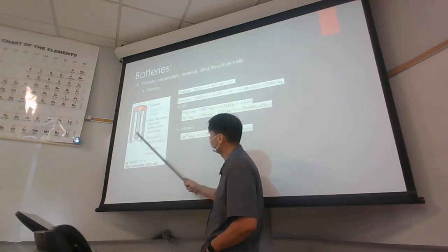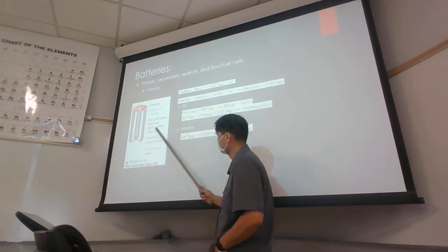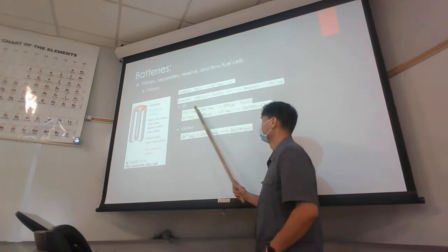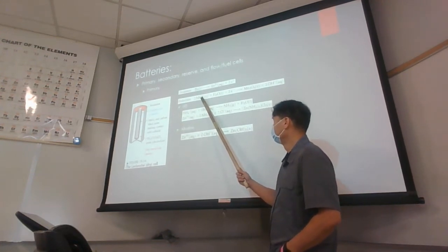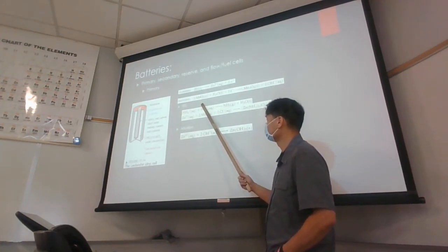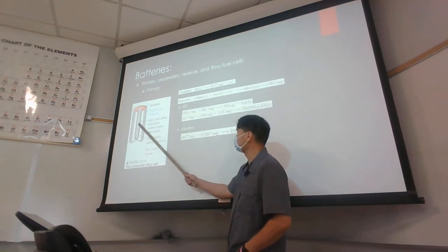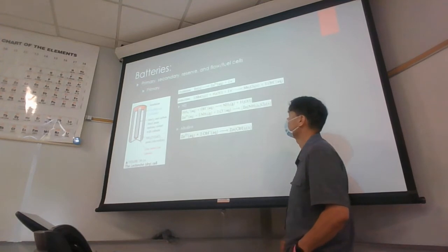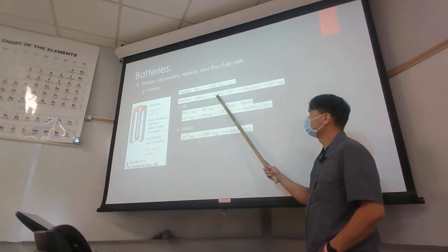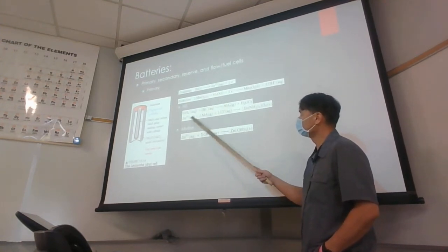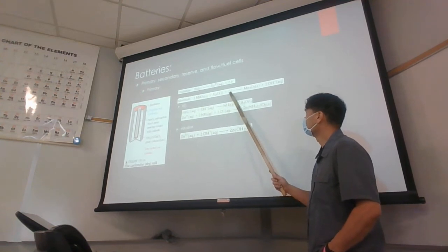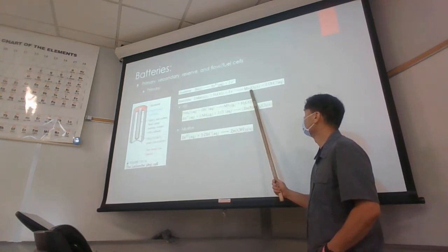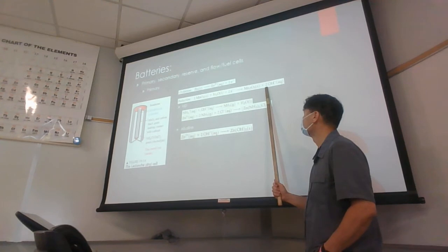Graphite's a conductor of electricity. And so as long as the crystals of MnO2 are in contact with the graphite paste and the graphite paste is in contact with the graphite rod, then we have electrical contact. And the MnO2 will take some water from the paste and 2 electrons from the electrode to form Mn2O3 and 2 hydroxide.